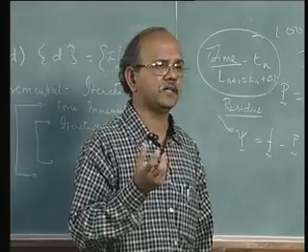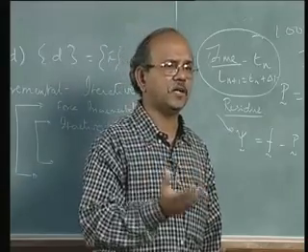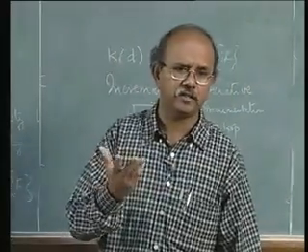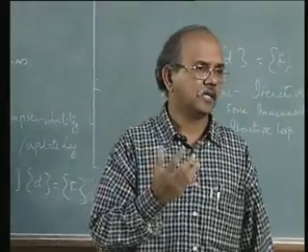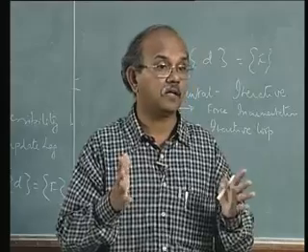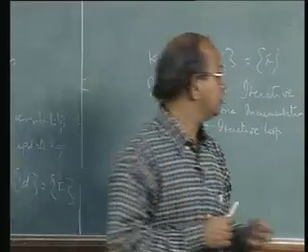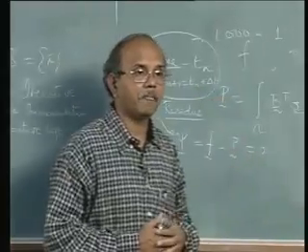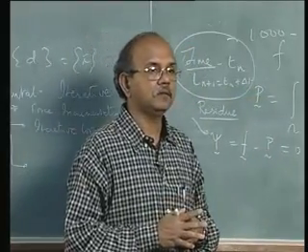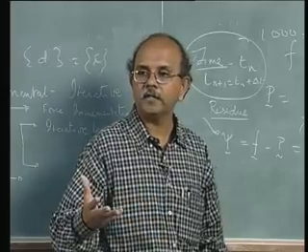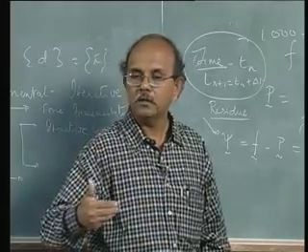Usually it so happens that if it does not converge within say 16 iterations or 20 iterations, you are not going to get convergence that easily. That means your time steps are large. So what the software does usually is to cut down delta T. If it had used 0.1, then it would realize quickly that at 0.1 I am not getting convergence, so I'll cut it down and go back to 0.05.